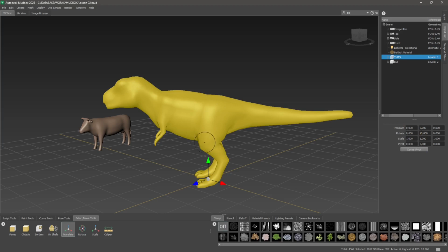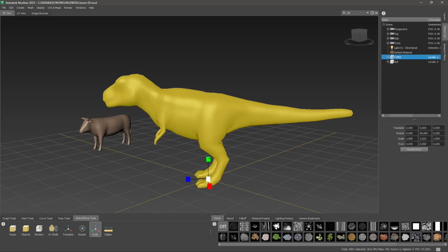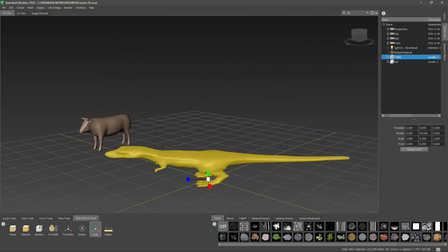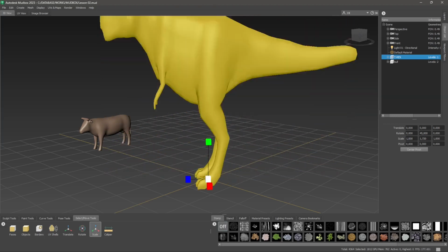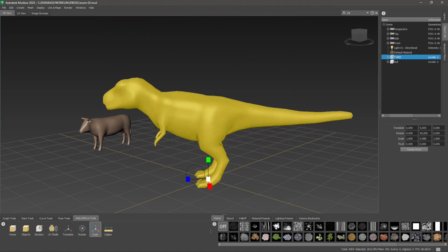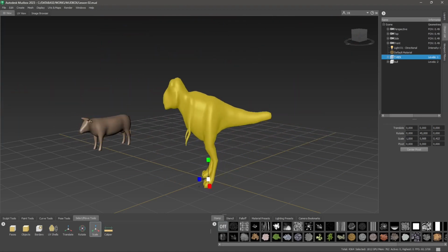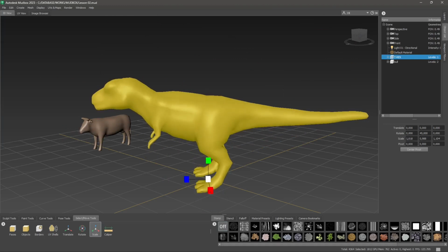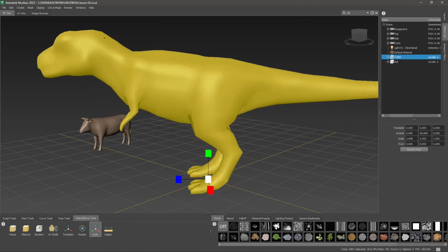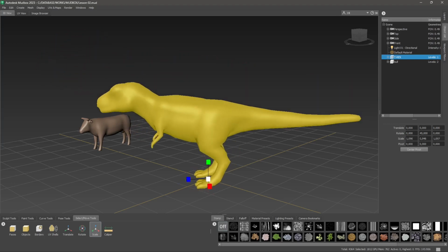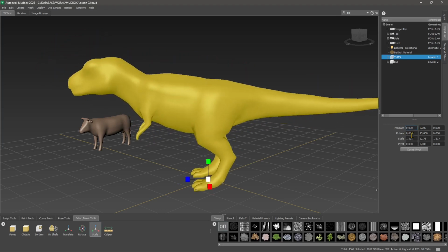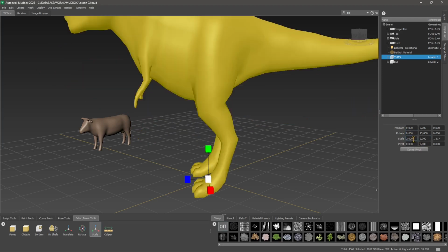And so now you can see I can rotate, and the pivot is oriented to the object right now. So when you center the pivot, it's going to be centered. And now I'm scaling in one dimension using the color squares, or if I use the white square in the middle, that's going to be a uniform scaling, so 3D scaling. But again, you can also scale in 2D or only in one dimension using the parameters.